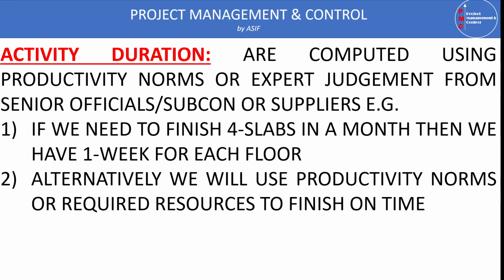So here we can understand that we can divide activities further so that we have manageable time. For example, as I said for the block work, survey and layout will not take too much time, so we do not define it separately. That's why we include survey, layout and engineering inspection in one activity like block work. This block work includes three or four activities, which is difficult to put in the program. For example, in our program the duration unit is 1 day, and this survey work will not take 1 day. So that's why we are not putting these activities in separately.